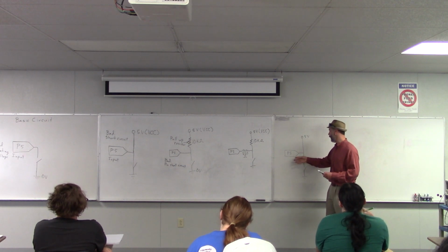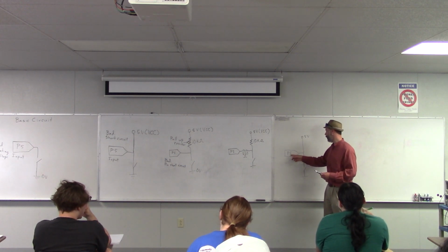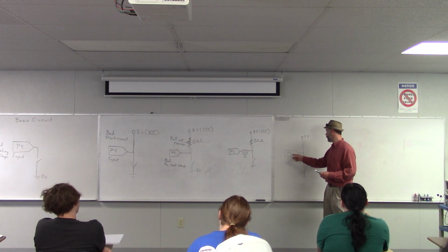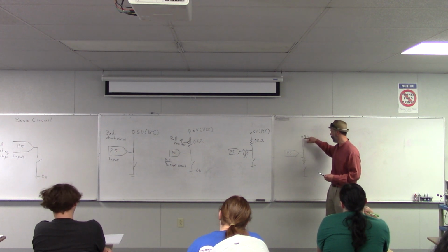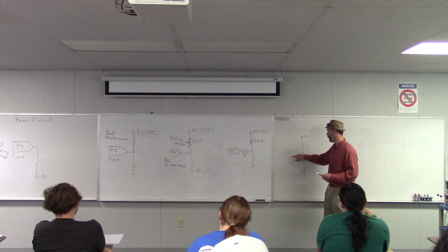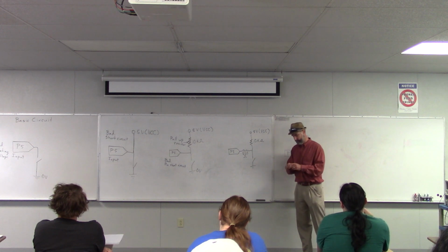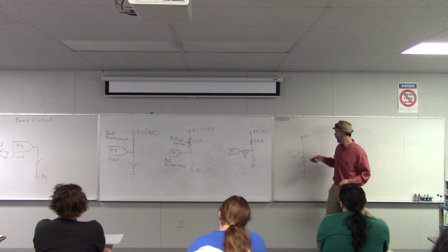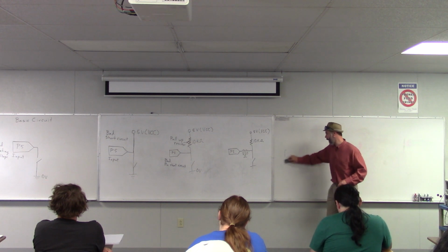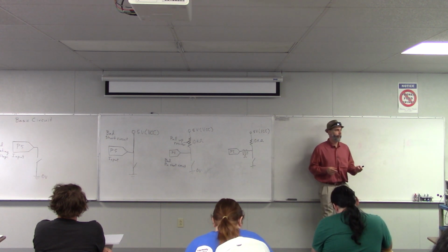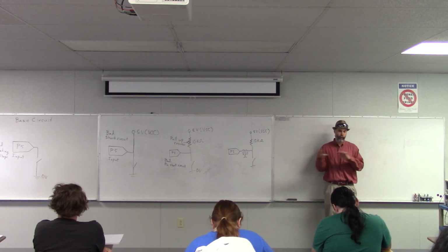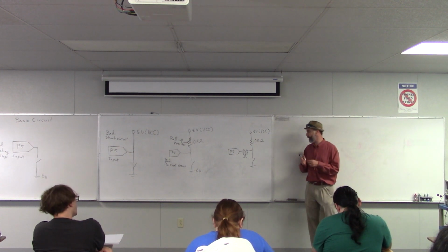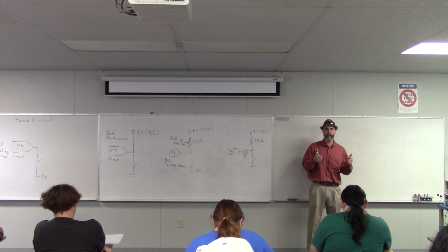In this case, if you made this an output and you force this to be low, then you would still have a short circuit from 5 volts there, and that could still damage the pin. So that wouldn't quite work, but I like the way you're thinking. There's often many different ways to make circuits, and often many different ways will work. So it's always a great idea to think about different ways you can do it. And if you can save a resistor here or there, simplify your circuit, that's awesome.